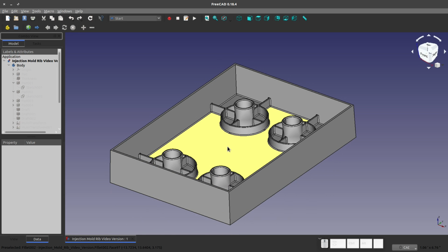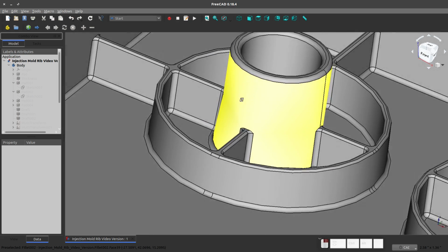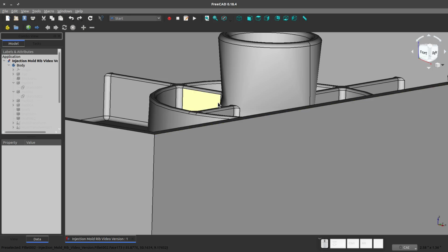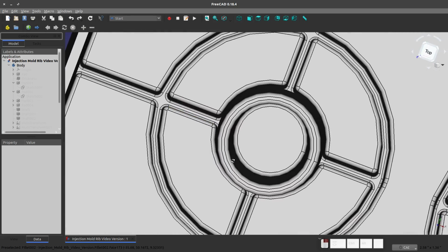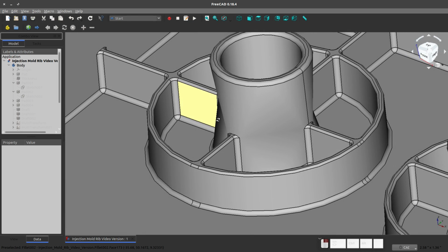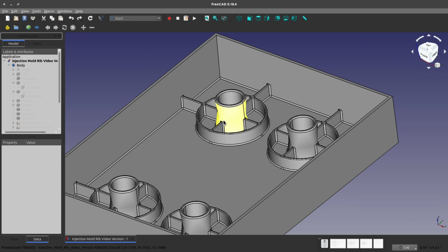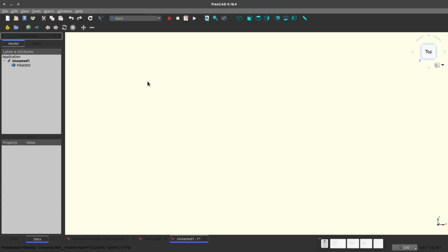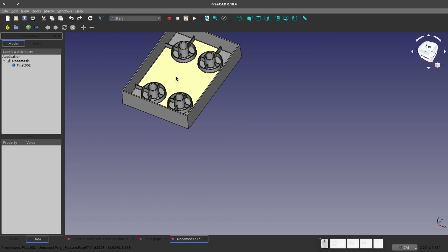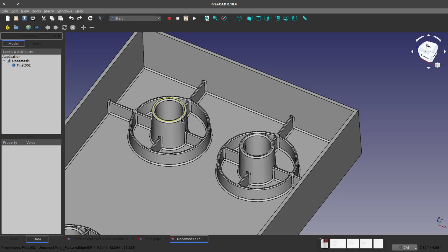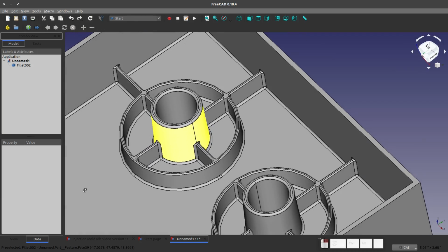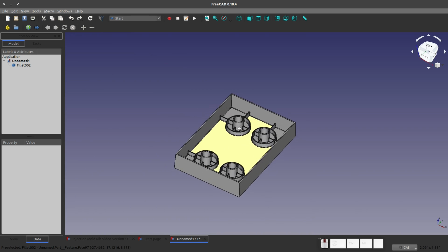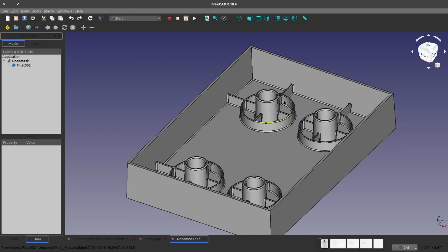Okay, I'm back, and you'll notice that there is a little bit of a bend happening in this boss, but that is simply a graphics error. That's not the actual model that we're looking at, so don't be intimidated. If I export this to a step file, which I'll pull up for you, you can see that all is well with our bosses, so don't be alarmed by a graphical error. It's totally fixed because it's not part of the B-rep body. It's just like a shading error or something.